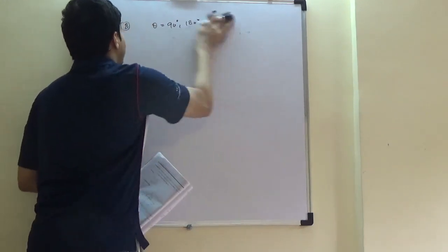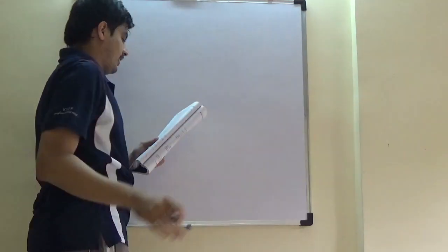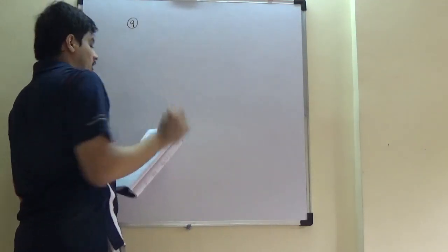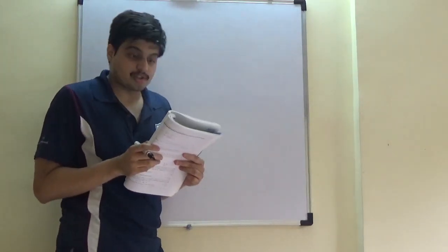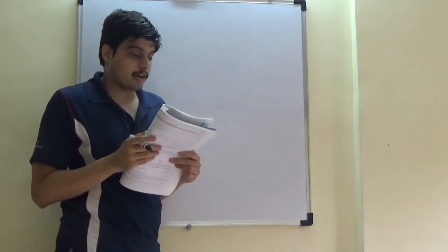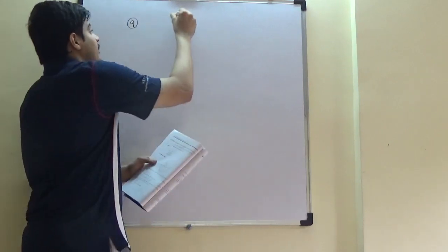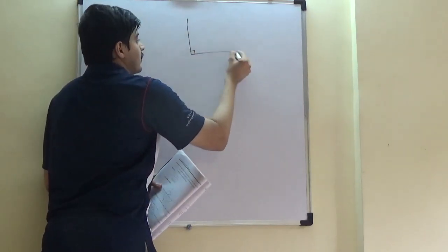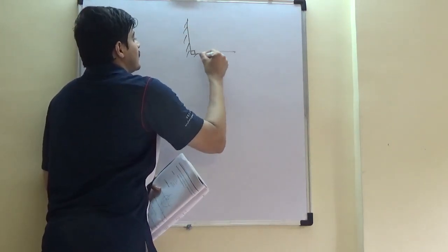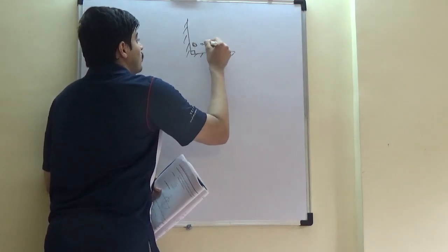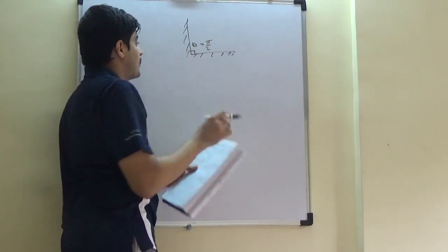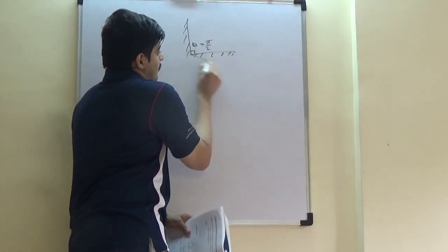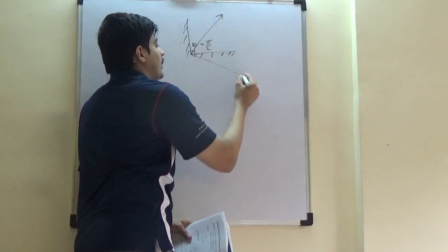Next question is slightly involved. It tests how much you have understood the imaginary component. What will be the potential function for a corner flow around two surfaces having theta is equal to pi by 2? So two surfaces are given, theta is equal to pi by 2, but this inclined surface is making angle alpha with respect to the horizon.